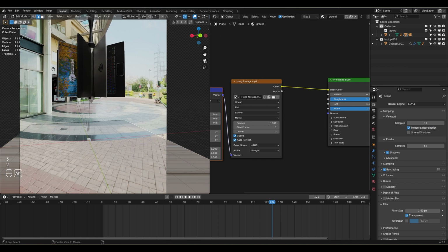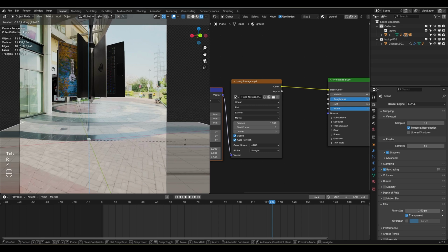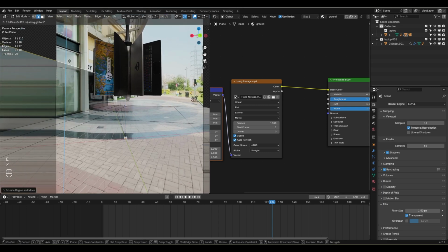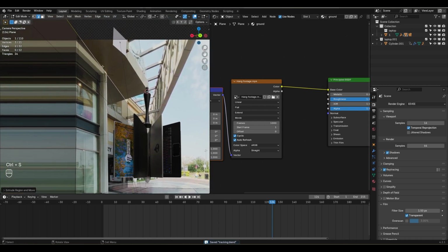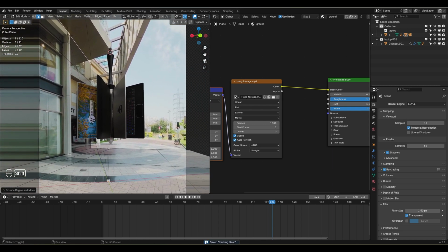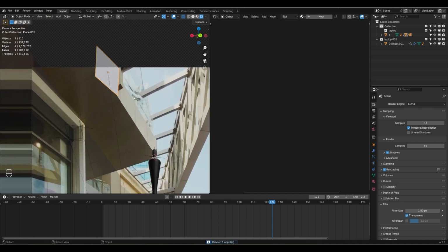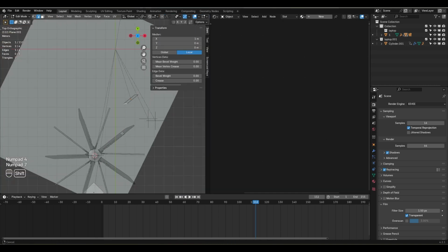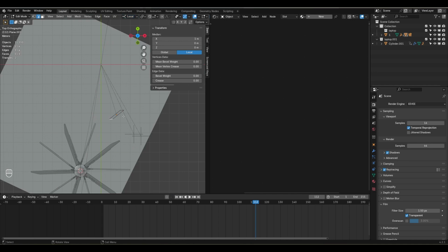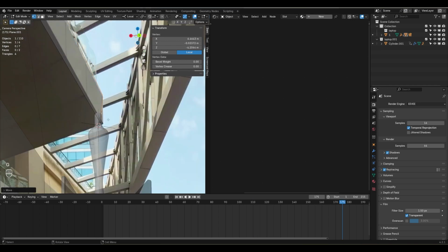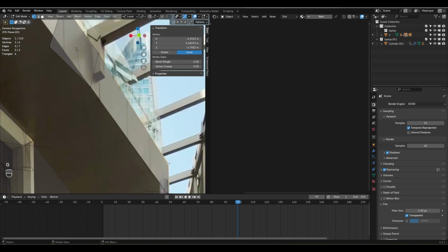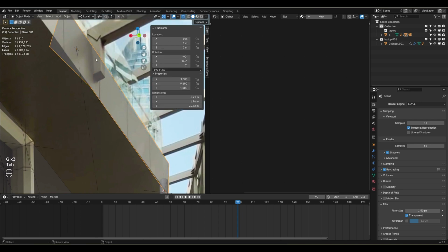and press 2 for the edge selection and just extend this edge, and if I want I can just rotate this, and basically I want to do from this side as well, and I want to create another box from this side. I already have a solid plane over here, so what I can do, I can go to this top view and change this to local, E, and just locally extend this, G Z, and manually I am going to align these things. We did not align this properly the same way, but we have a reference.